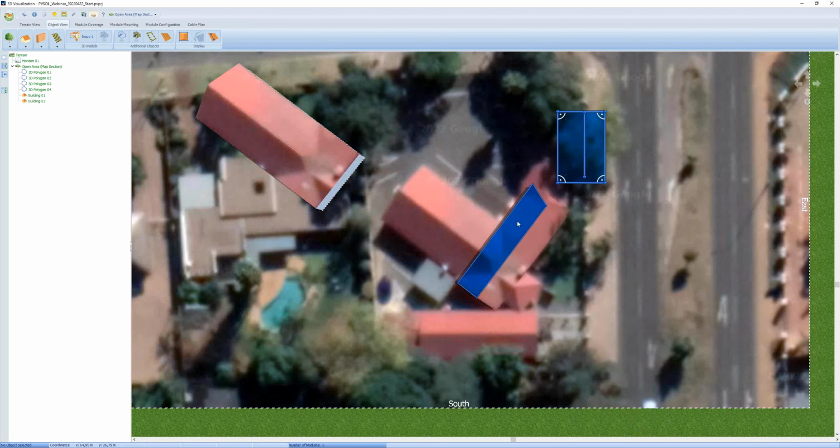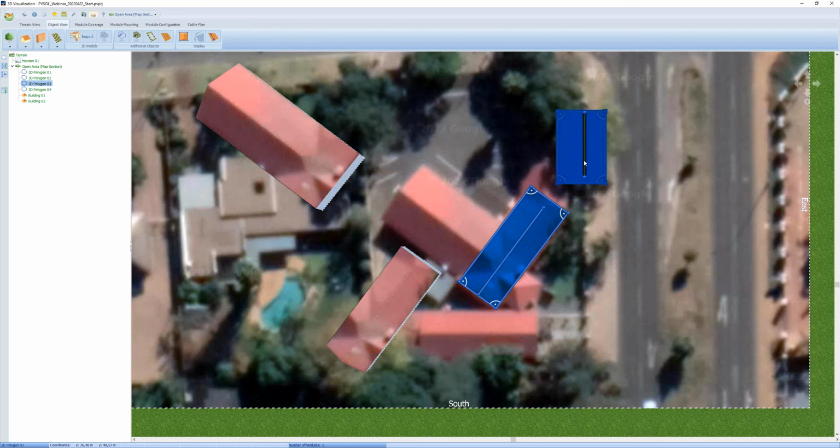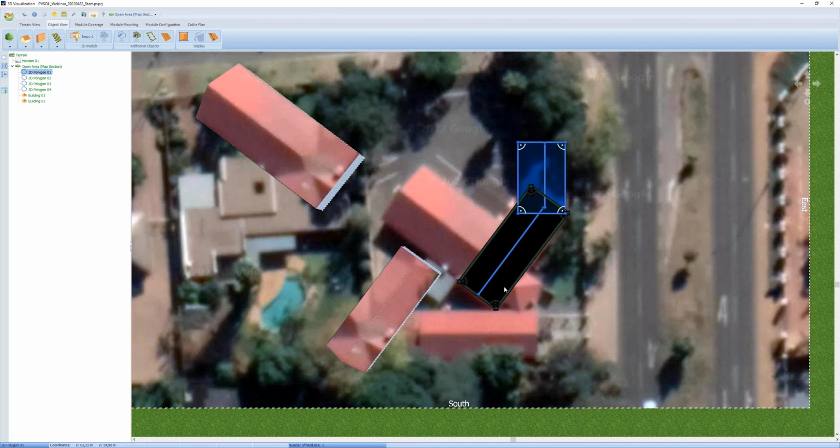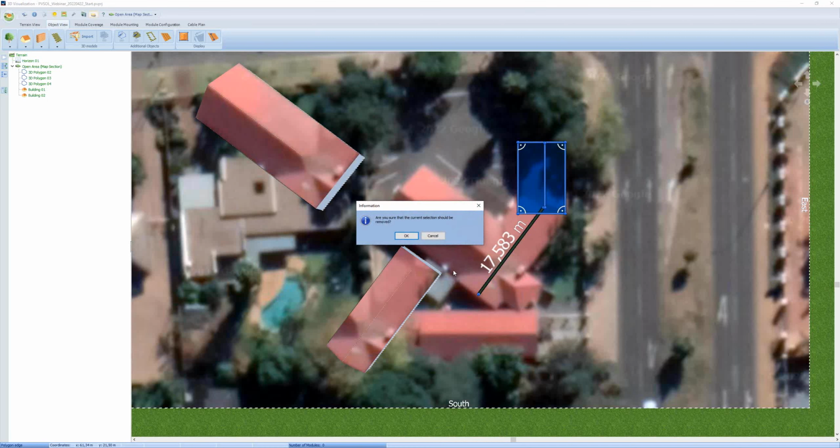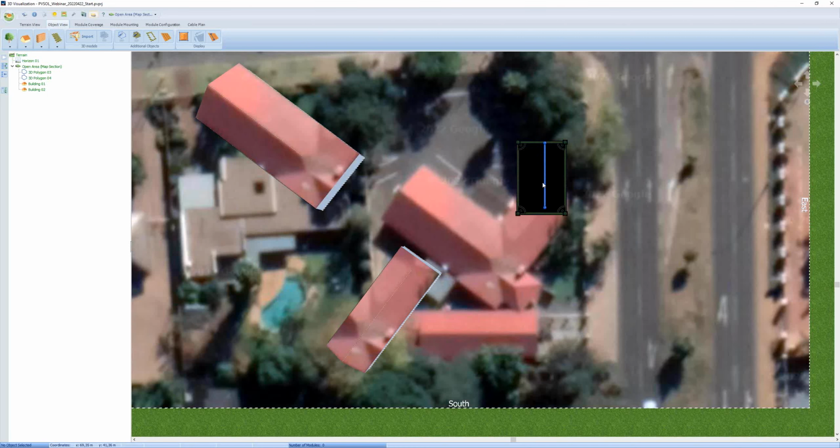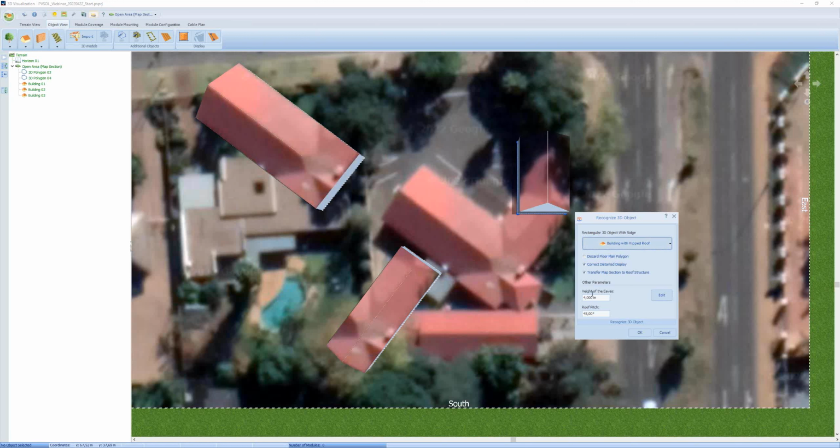So we move building 2 away. And now we have to place our third polygon again. Yeah, we have to bring it in position. Then we have to remove the second one here. Remove. Also the ridge, remove. And then we can extrude building number 3. It's also a hip roof with 3 meter height for the eave and 25 degree.